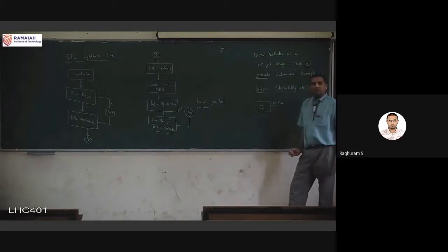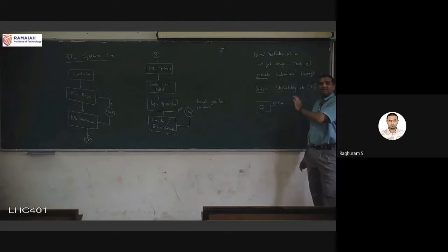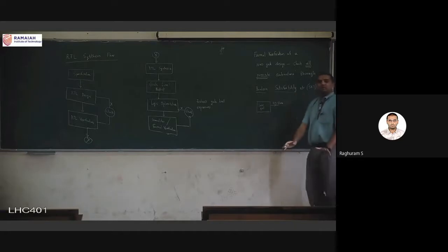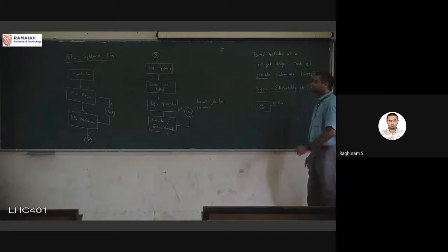In formal verification, we can ask a question like this to the solver. It's called a satisfiability solver. Does this block, given this netlist, satisfy output equal to 1010? Just tell me yes or no. I don't care about the input combinations. If this block satisfies 1010 and the solver gives yes, that means there is some input combination, maybe you can get that input combination, which is producing this output 1010. There is a problem. That is the main advantage of formal verification.